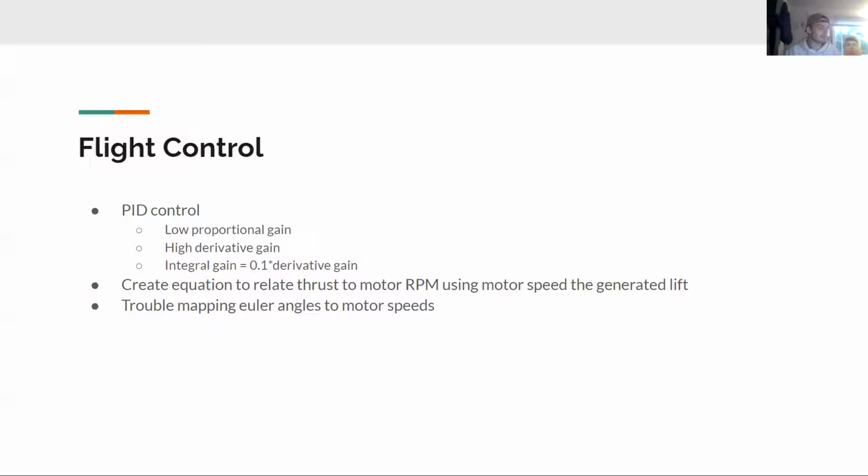down to one constant. Basically that K value takes into account the fluid dynamics of air on top of the rotor and underneath the rotor, the weight of the chassis, the geometry of the propeller blades, the nominal lift diameter, and so much more, all boiled down to that simple constant, which I just got through testing.